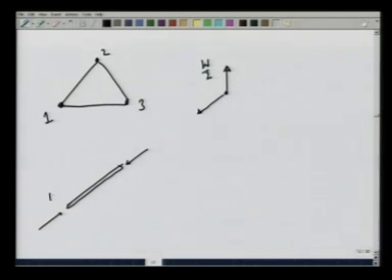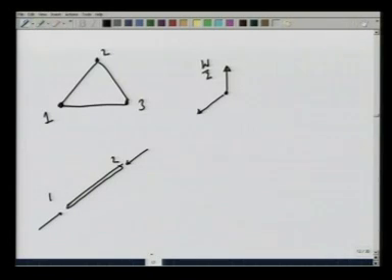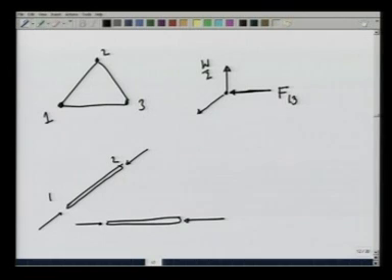Similarly, the force on 1 3 that I made was also pushing the rod, that is, the force is compressive, so the force acting on the pin would be in the opposite direction. So, let me call this force F 1 3, and this force F 1 2, and this pin is in equilibrium under these forces.